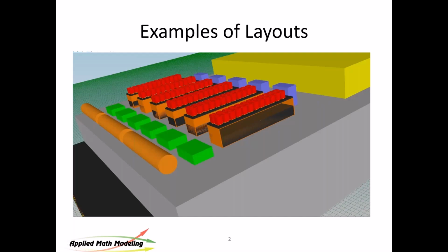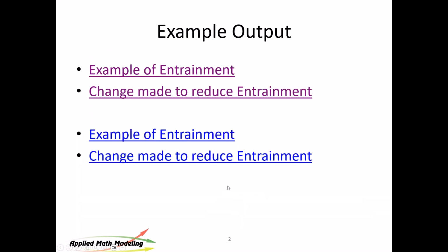Another example here. Now, in this case, there's some structures in front of these heat exchangers. I think the goal here was to get these further back on the roof so that they're not being contaminated. This is the same variation of the same design I showed you before. The generators are down here and they're blowing heat up over this edge. It's okay to have other stuff up there, but let's keep the heat exchangers as far away from that hot air as we can get. So I'm going to give you some examples.